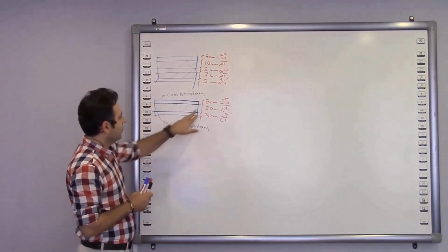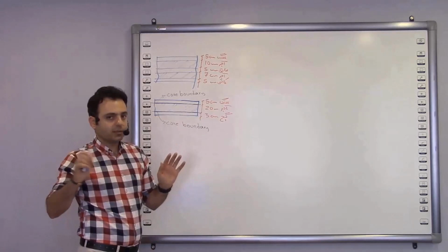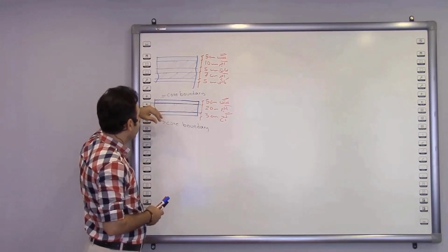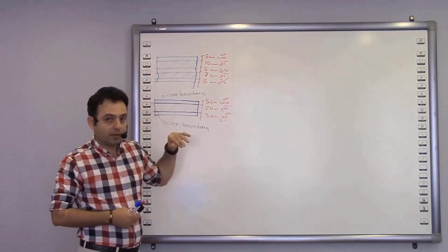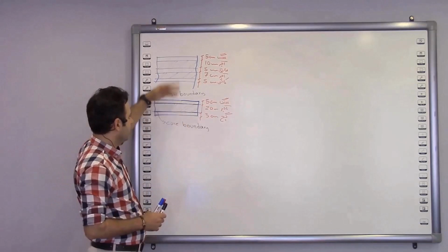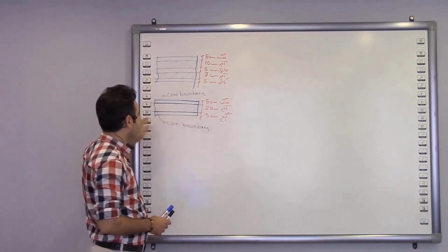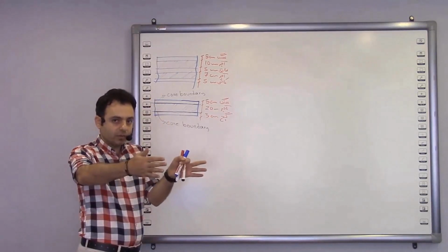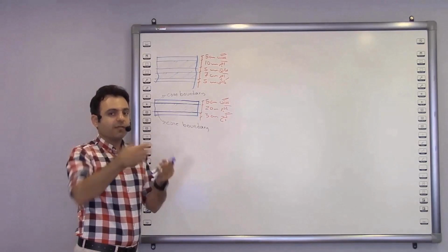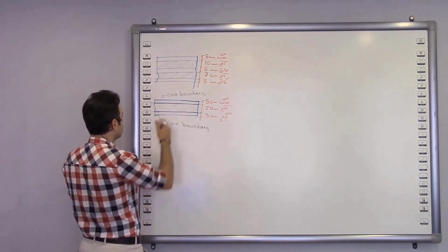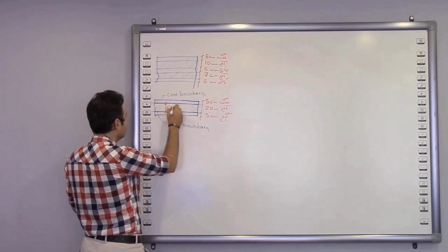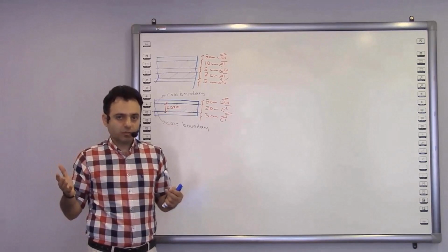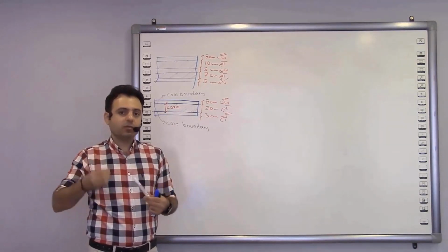Check this out. We have a boundary here which is not real. It's a virtual line, and it determines that finish, for example, goes that way and the structure comes this way, or separates the finish from the structure. And we have the same thing on this side too. Kind of create a zone that there is only the structure and the insulation in it. That zone is called core. So the finish does not place in the core. And its main job is to make us know that the finish is out of this zone.